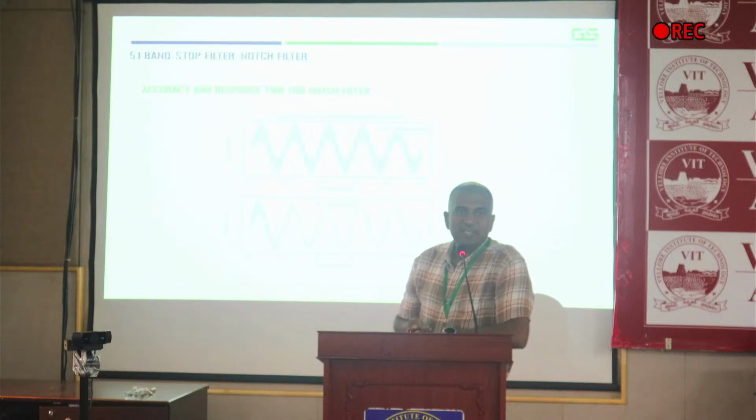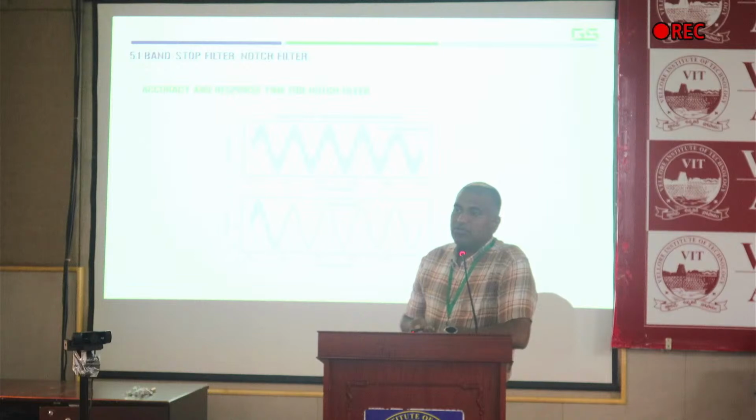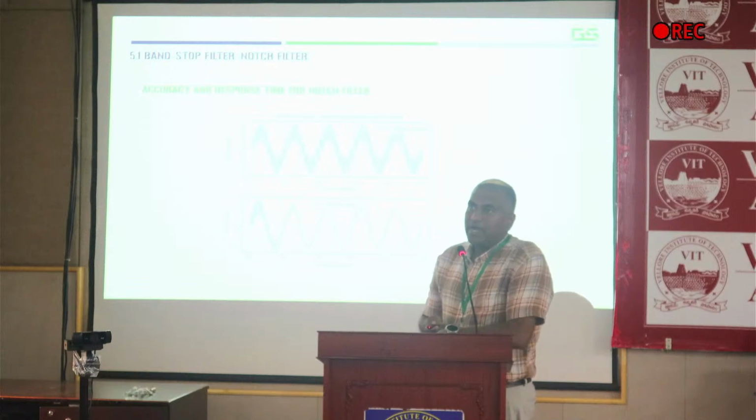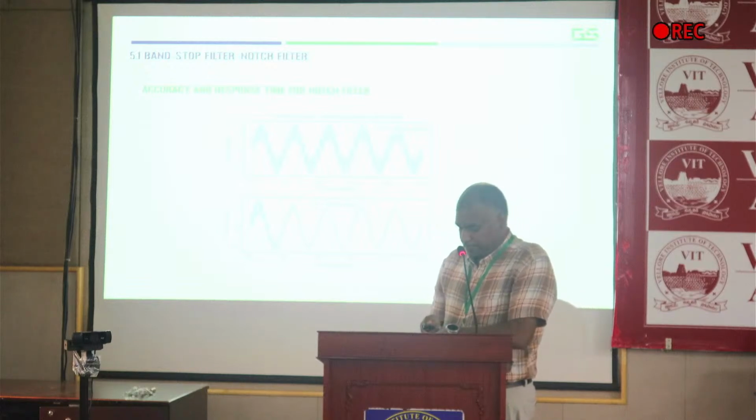We use STM32 boards to process this data. If you see here, to get the regular data, it took a 0.4 second delay. Actually we should reduce this delay to get accurate results in time. That is one of the challenges. But when we use the bandstop filter, we have this delay.